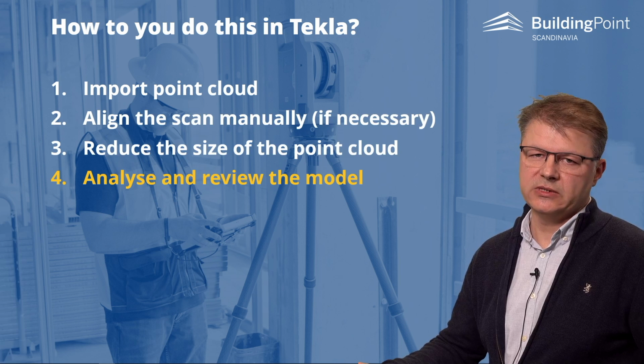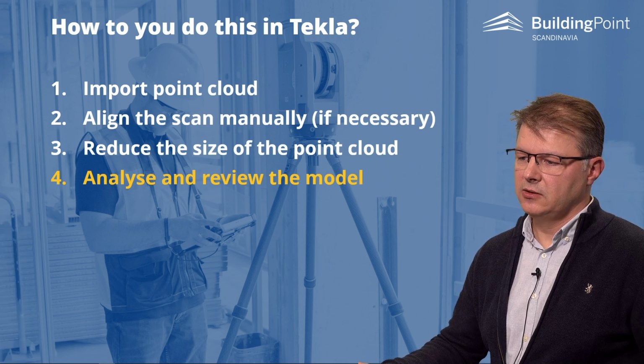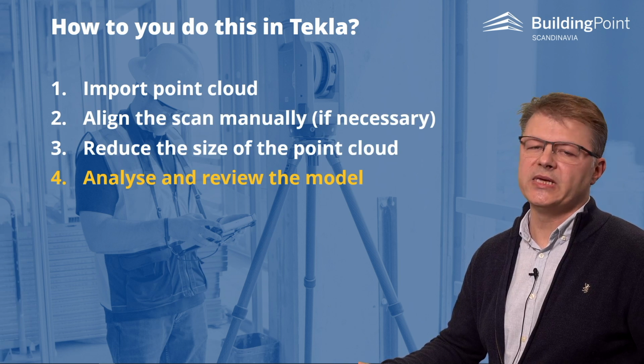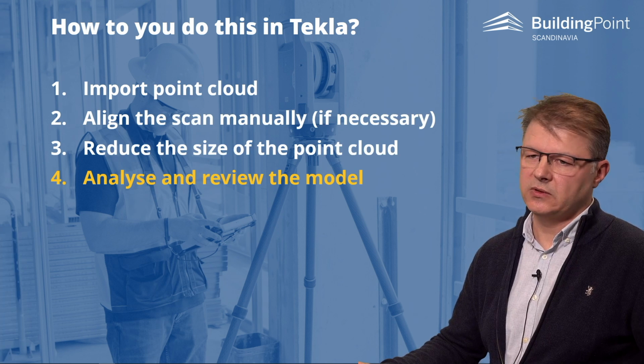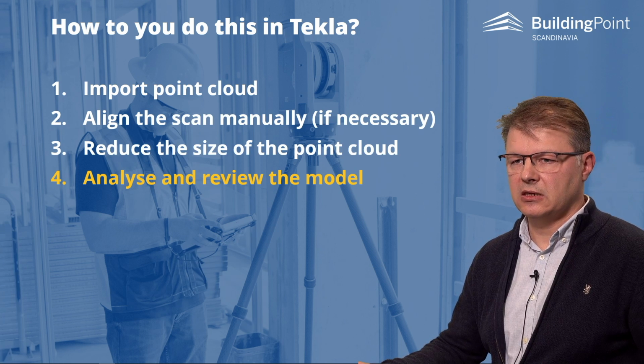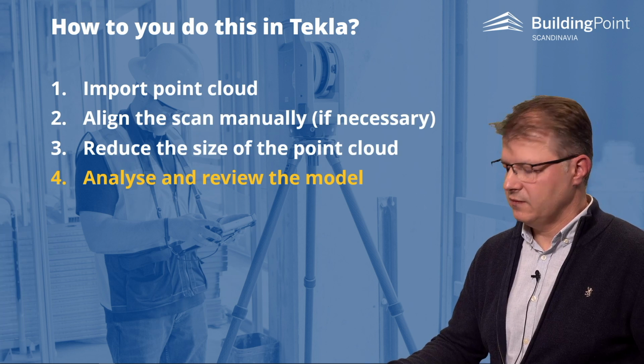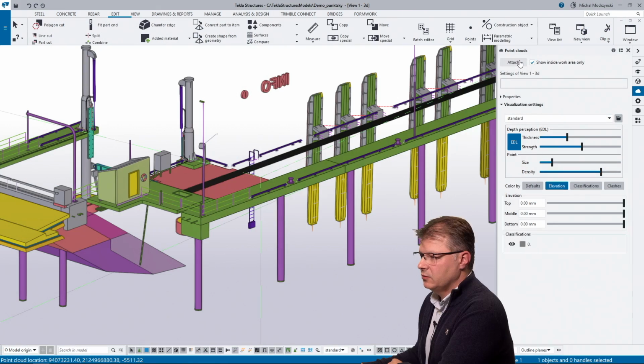When the point cloud is imported and placed correctly, you can do some basic analysis in Tekla. You can check different levels. You can use the class check in Tekla and different stuff. That's going to be in my demo as well. I will try to attach a point cloud.